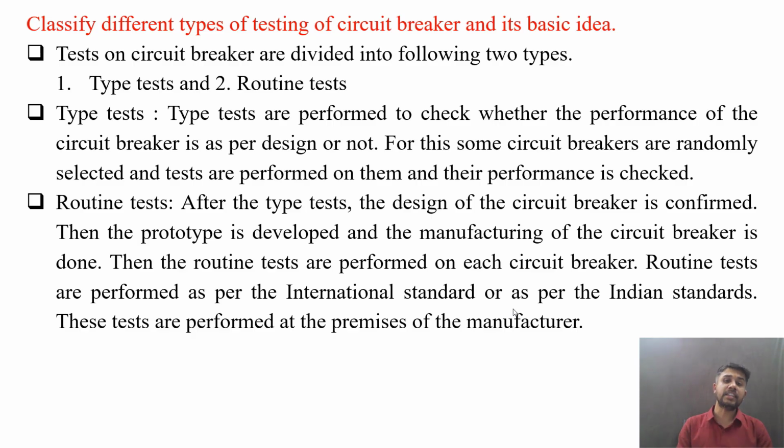Then the routine tests are performed on each circuit breaker. Routine tests are performed as per the international standards or as per the Indian standards. These tests are performed at the premises of the manufacturer. So this is the basic idea of circuit breaker testing: to verify its operation and its design constraints.